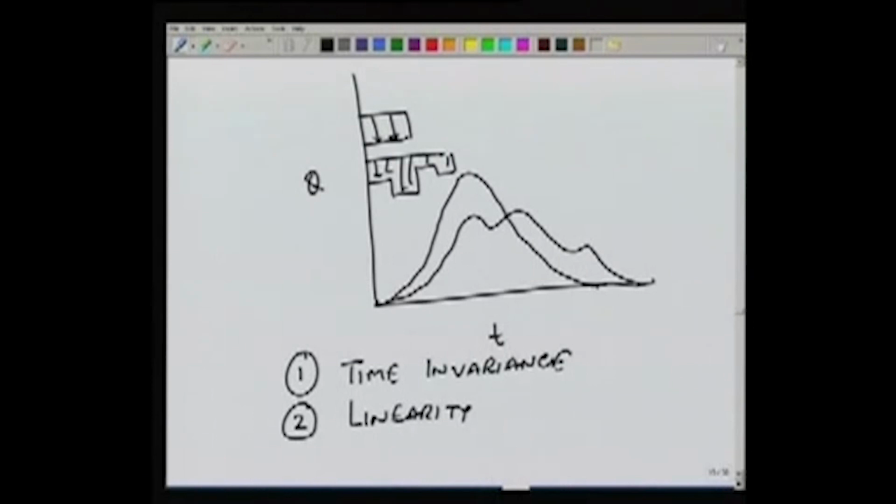In general, rainfall runoff relationship is very complex. If we have two different catchments, the same rainfall will cause two different or very different hydrographs. Or for the same catchment, if we have two different kinds of rainfalls, they will also cause very different hydrographs. Sometimes even for the same catchment and same rainfall, we may get different hydrographs.